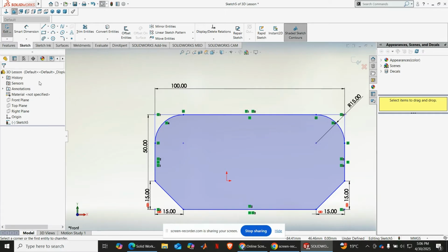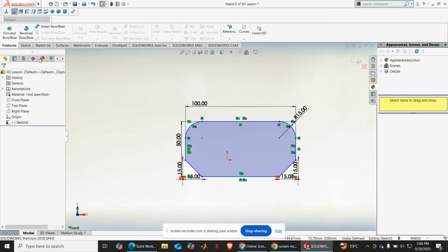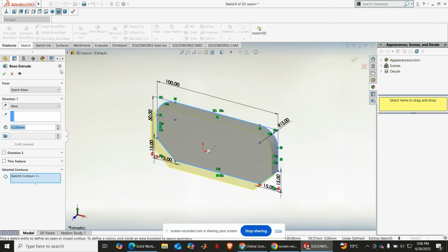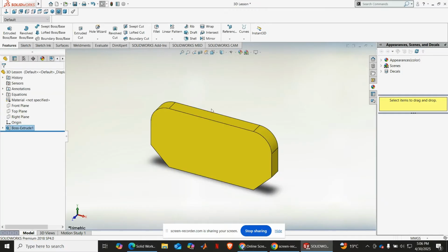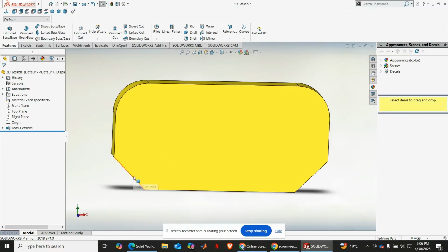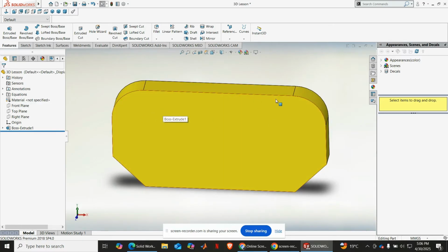And you see, when you extrude this object, say extrude feature, extrude base. So extrude by 10, check. So you see, you have your feature here with fillets of R at 15, and with fillets too of 15. But we could also do this as we would in 2D.